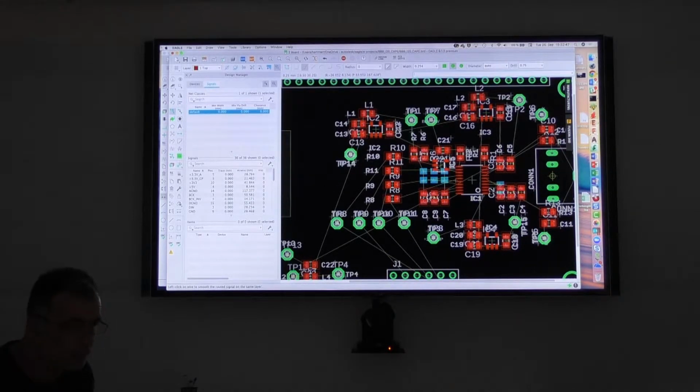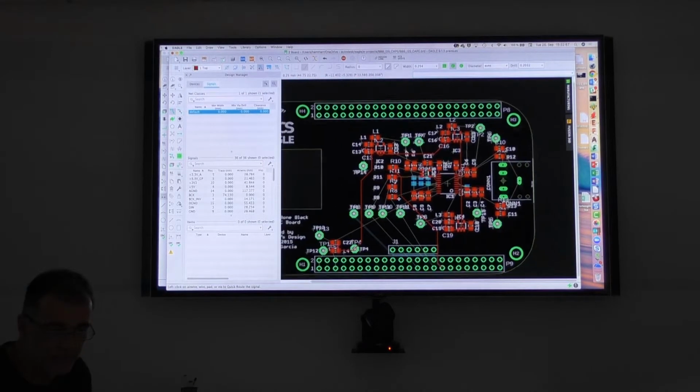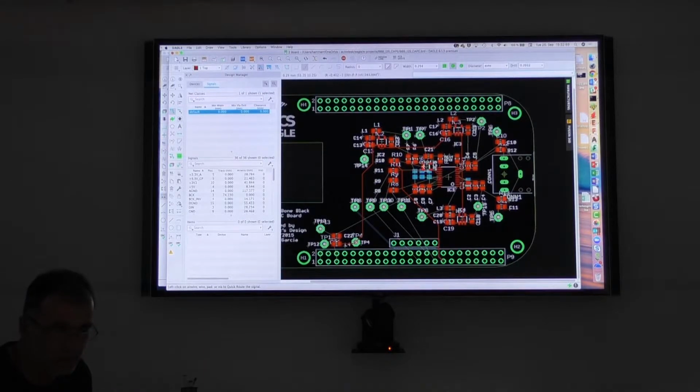Okay, this could be routed. Okay, so I have some stuff here, and now I simply start a router. The signals that are already there, they will remain untouched. So this will remain as it is. So you could route your critical ones and then, if you're less fussy about the rest, let them also route.